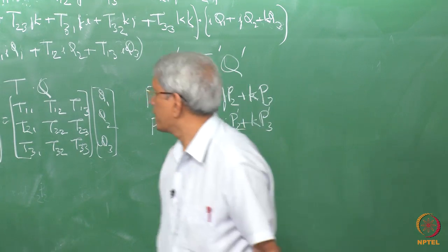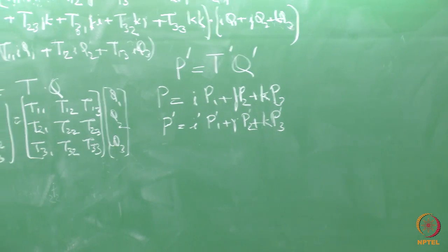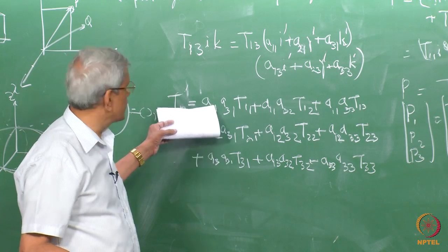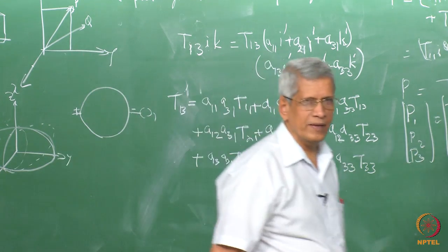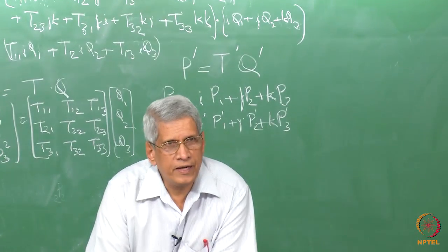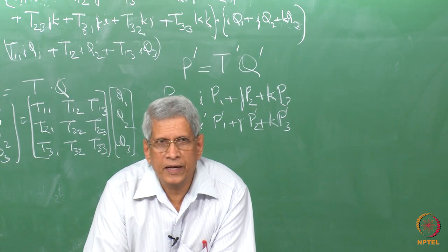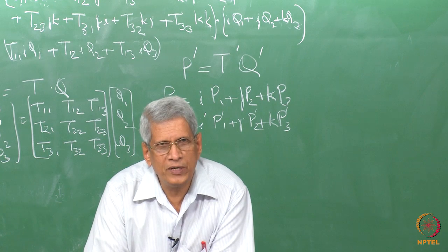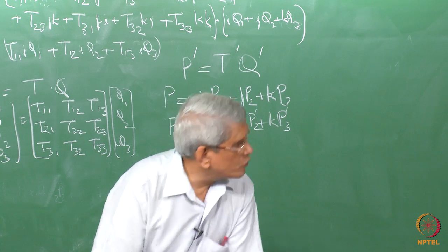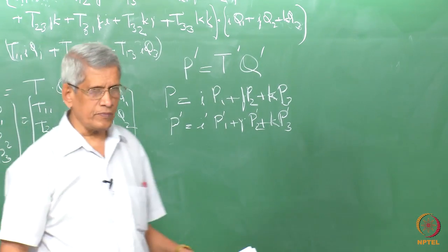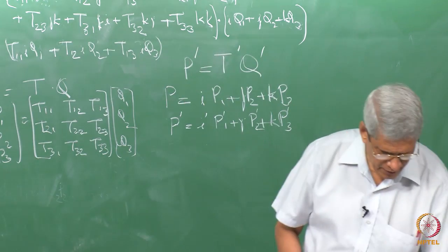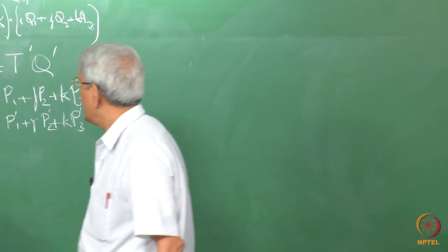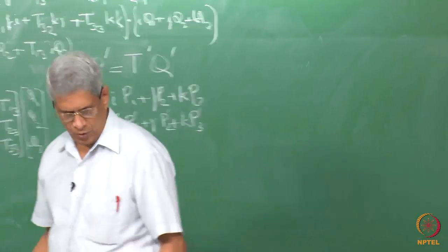Not only that, you can see that from the coordinate transformation matrix which we use, this is getting repeated, correct? This way it can be done. So for all other 9 components we can write it, and we will have essentially 81 terms. This is going to be a very laborious way of doing it. So if we use the Einstein notation, then the job becomes much simpler, right? So how can we go about and do it?